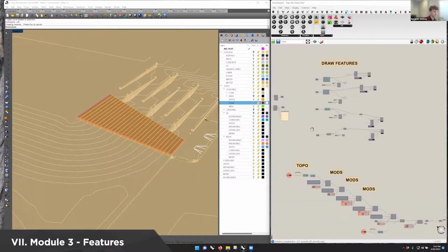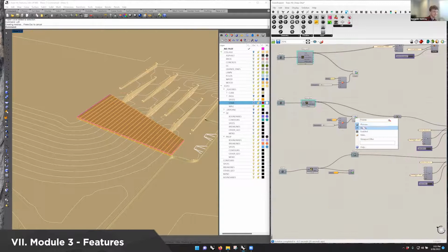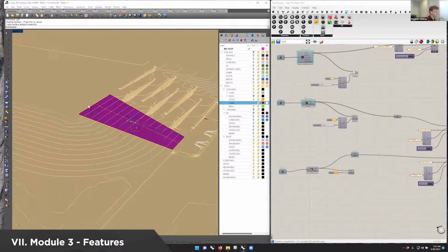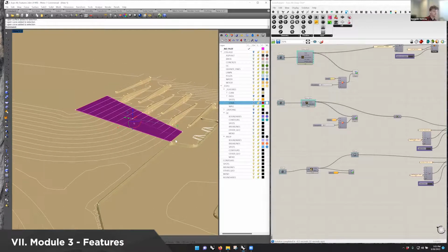I'm also previewing states. It will create a surface between those two curves that is actually oriented the way that the stairs component processes the surface. If I had created this any other way, the stairs might actually go sideways. So we typically recommend using two different curves, and you can do an arced curve. It doesn't have to be a straight curve. I think Chris will show you an example of how to use an actual arced curve to create a curved staircase.